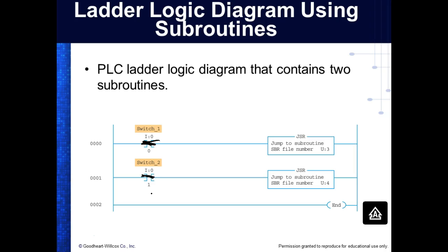No. Why would it jump to ladder? This is ladder 2. Once it jumps to this subroutine, it would go out and run the subroutine. So this came out of ladder 0, right? Okay, so where's it going to come back to? Run 1. And after it does everything it says in that one, it's going to come back to hopefully 2. That's what I'm saying. It comes back to 2, and it hits the end. What would it automatically do when it hits the end? Go back to 0, because we don't have to toggle it.